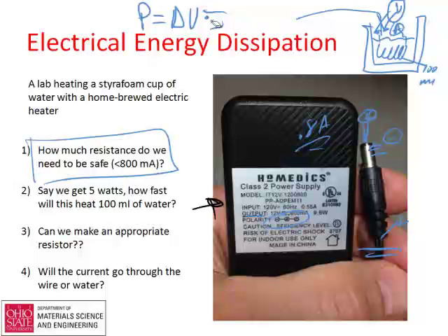Where does that power go? That power turns into heat. And 1 watt of heat is basically a volt times an amp. So you know how many volts, how many amps are you going to be at? 12 volts, you're going to be something like on the order of half an amp. So you're going to be doing something like 6 watts. This thing can't go beyond 9 watts.